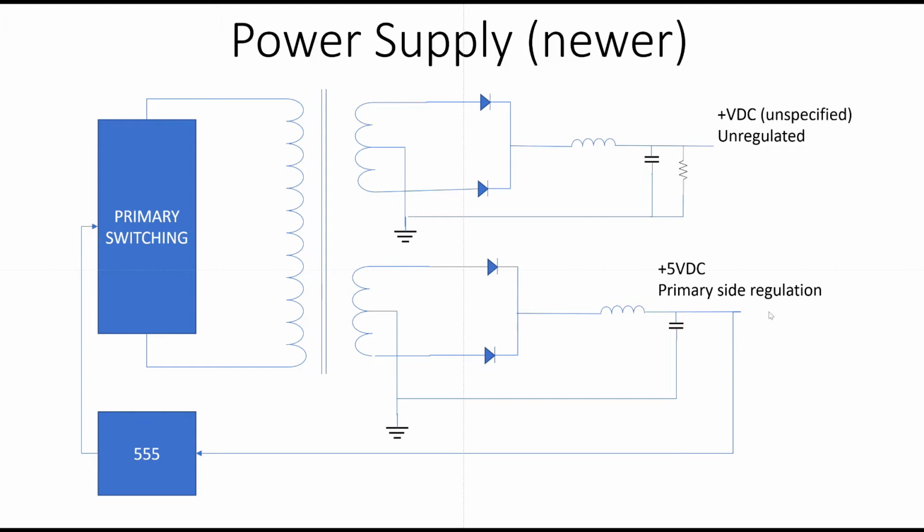Now, I have subsequently looked at this in circuit, and this is about 600-700 milliamps on the 5 volt side, and that gives us about 14.4 volts on the plus and minus volt DC outputs. So that's pretty good, but also it fools me. I will admit to being caught out by the fact I didn't spot that there was now a bleed resistor in this circuit. So anyway, let's go back and fit the new board into the device and see if it works.